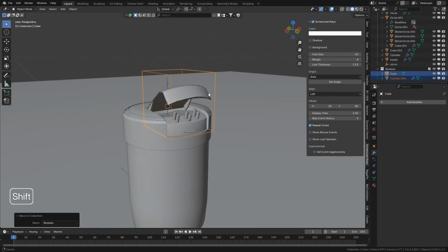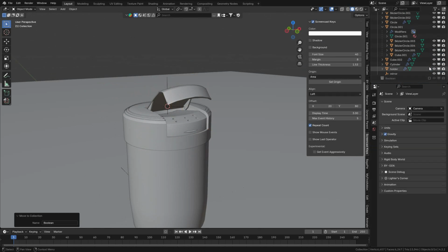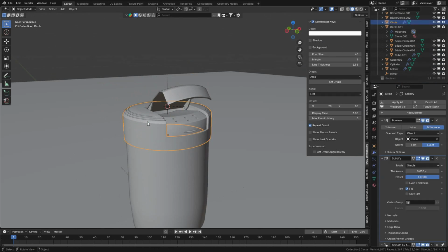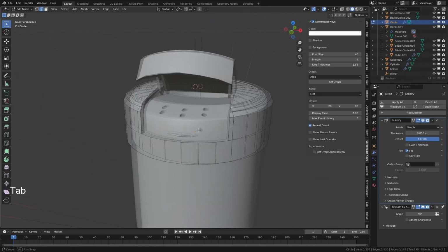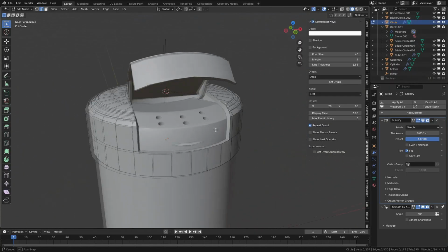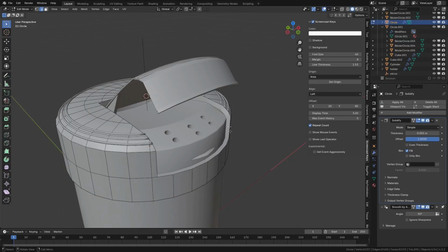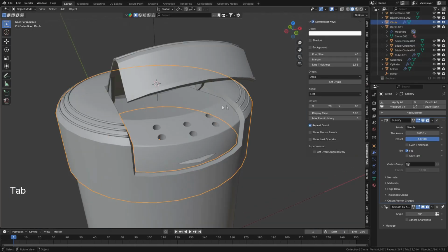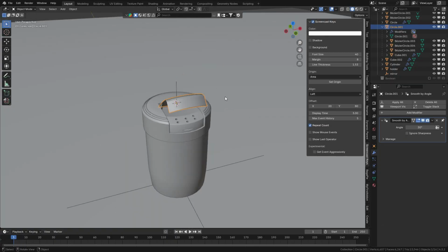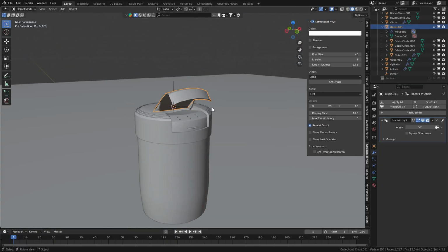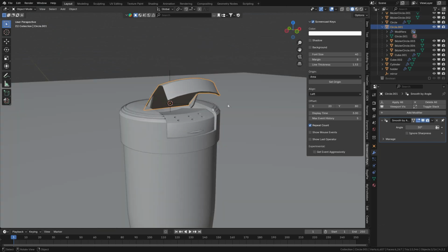OPC. So now that this has been created, we can hide them here. On checking this, go to this, and we'll click. For now, you can just apply a Boolean modifier. Click apply. Then we go to edit mode. Everything has been nicely applied here. Alright. Can do the same for this. There's no modifier on that. I think that'll be all. I want to try and fix this glitching problem.